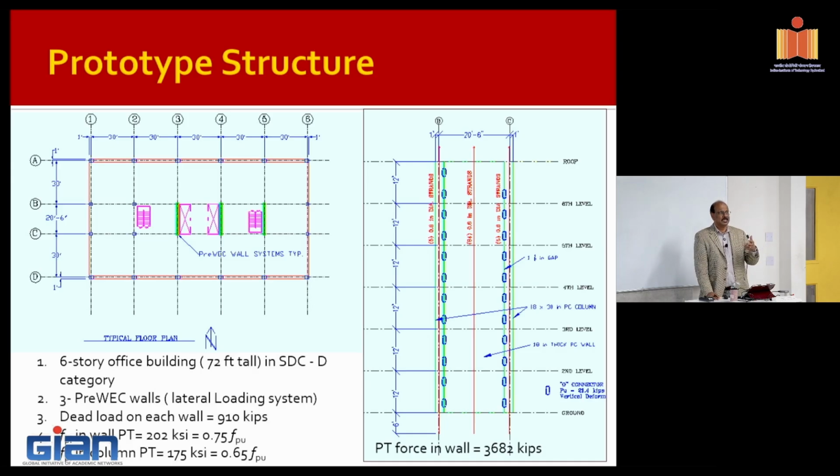When you do testing in a quasi-static manner, like I've shown you, we test push and pull slowly. That basically doesn't induce any velocity-dependent behavior, so you don't get any velocity-dependent damping. In that exercise, what we try to do is quantify the amount of static hysteresis in the system, right? If it's a column, you're pushing and pulling, plastifying, it tells you what the static hysteresis is.